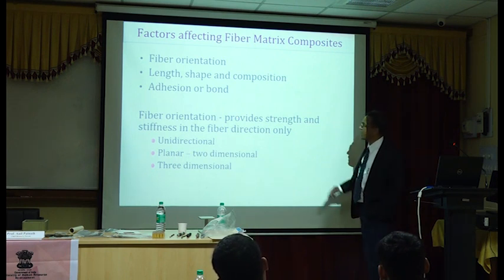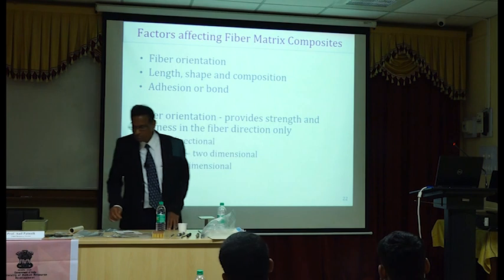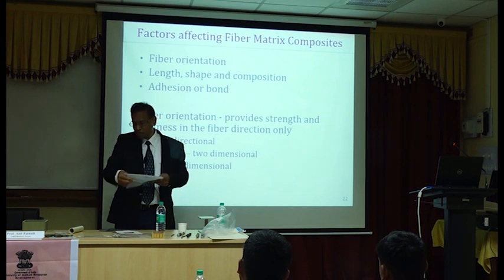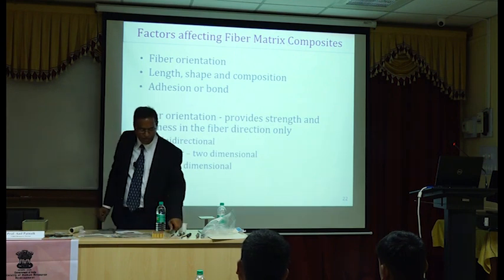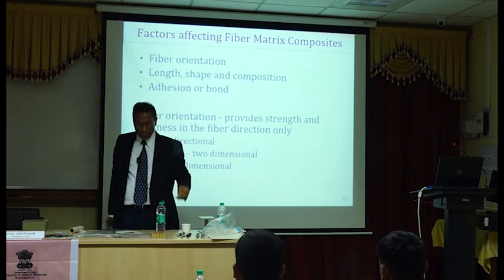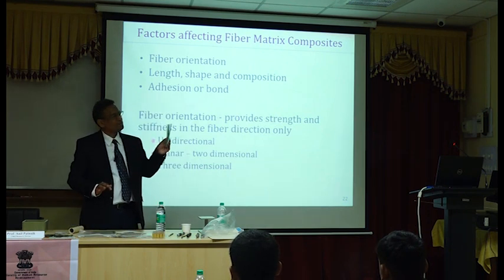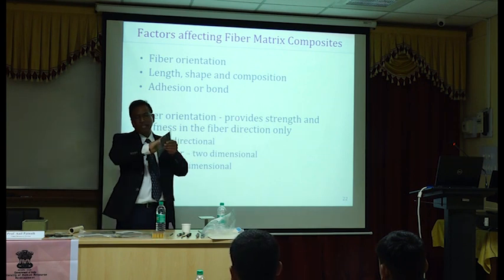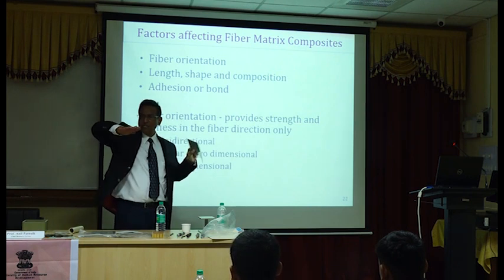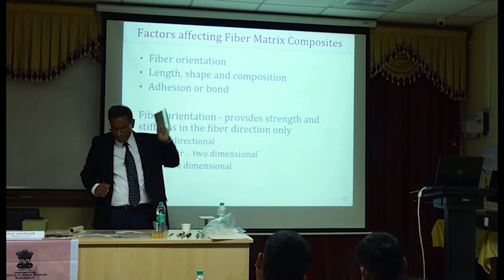direction of the fiber. Okay, so you can have fiber only in one direction. When you come and take a look, you can see all the fibers here. So sometimes you have fibers only in one direction. Reinforcing bars generally have fiber only in one direction. Plates, such as this one here, have many layers, and these layers have fiber in different directions. So each layer has one direction, so it gets strength in all directions. That's the whole point of this panel here.